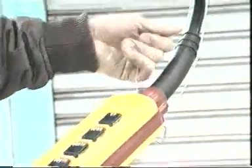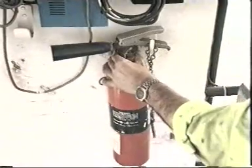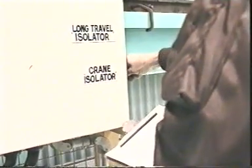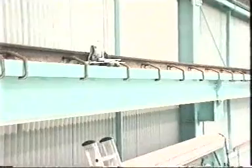In the case of cabin-controlled cranes, make sure that the cabin is in a tidy condition with tools and materials properly stored. Grease, oil spills and debris on floors, access areas and ladders can be hazardous and should be removed. Also check to see that the fire extinguisher is in place and satisfactory for use. Before engaging the power, make sure that auxiliary isolators are in the off position, that all controls are in neutral, and that the travel and traverse rails are free of obstructions and faults.